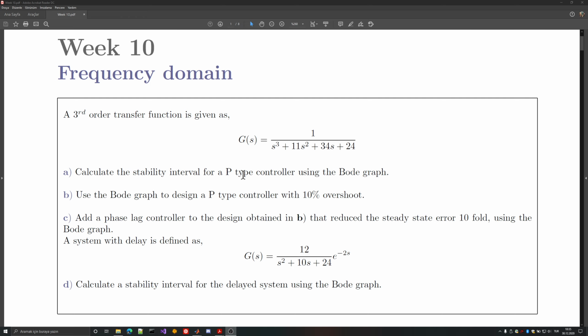But since the Bode plot is a logarithmic plot, and if you know some relations in your feedback structure, let's say you have two transfer functions and you know that you are multiplying them. The thing that you can do is, if you know, let's say experimentally, one of the transfer functions' Bode plot and you know the other one's model, then you can work out the multiplication Bode plot by examining both systems separately, and then multiplying the gains and adding the phases. Because you're dealing with complex valued functions, you can easily work out Bode plots that you don't have available, but you can create them, or you might just look for a certain point for that multiplication of transfer functions, and find individual points and then work out the relation.